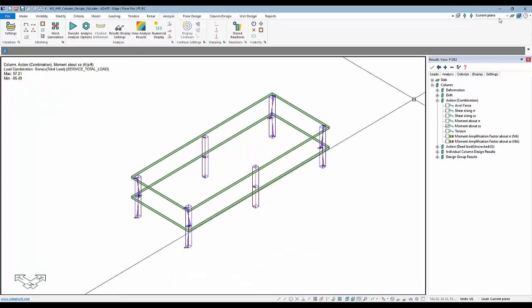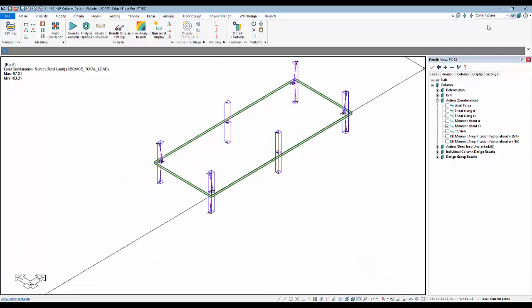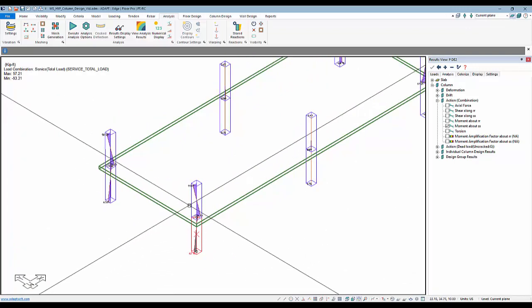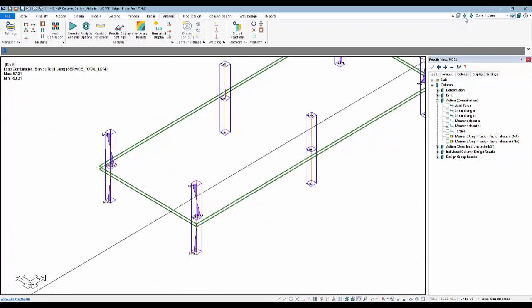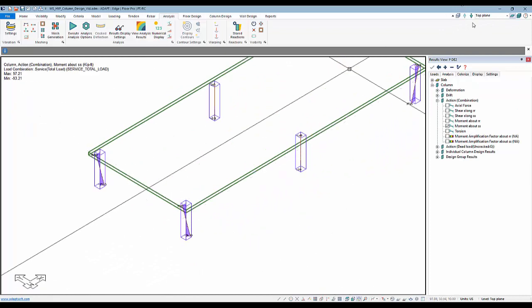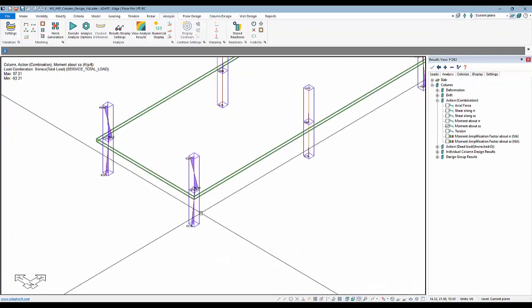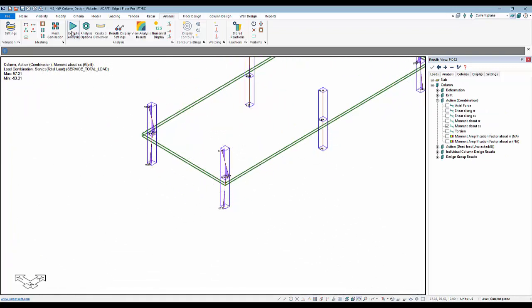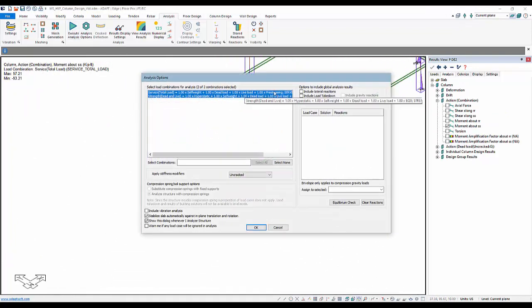And now what I'm going to do is just go to the level I want to design the columns for. So in single level mode, I want to design this column right here. If I wanted to design this column, I would go up to this level. Okay, so we're designing this lower level of columns, for example, and I'm going to rerun this model in single level. You'll notice in single level the program filters out PDelta, so I can't even obtain a solution for PDelta in single level to begin with.